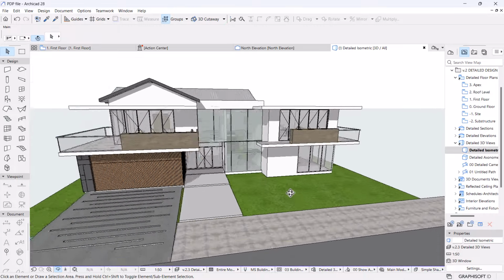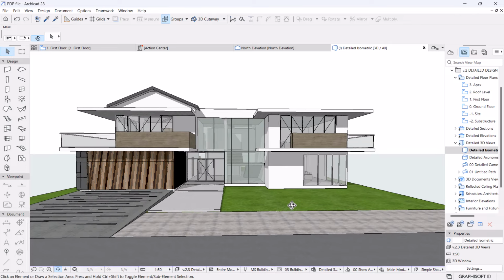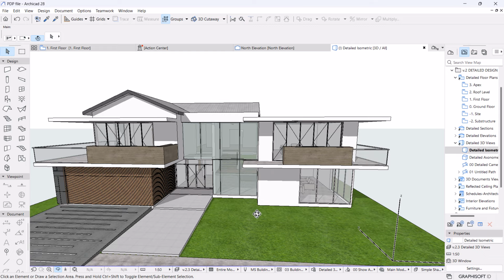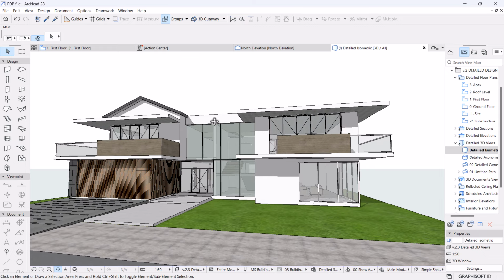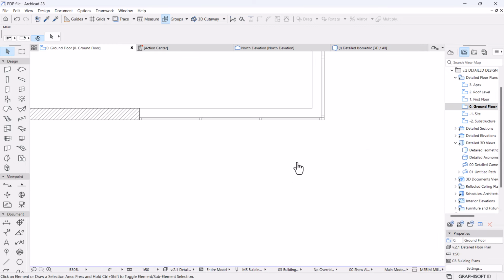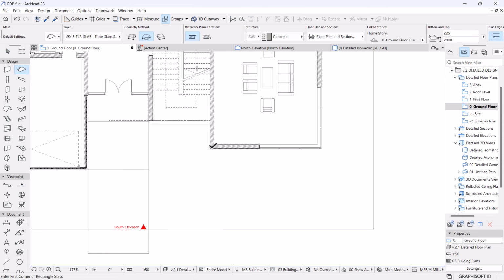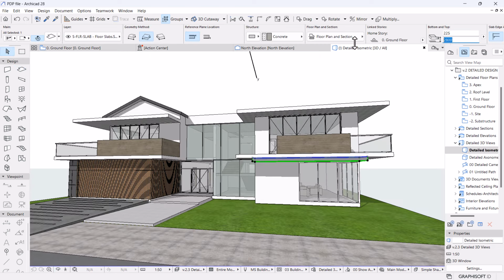That's very impressive. We're now going to add final details that will make this look good. Let's start by placing our planter. We have our planter here down below, and then we have a feature column for this. So let's do that. I'm going to go to the ground, activate the slab tool here, and then draw the planter to there. But this planter is supposed to be on 0.